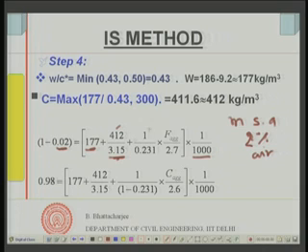So, that must be the volume occupied by all the ingredients, namely water, the cement, and the fine or total aggregate. This represents the total aggregate as we have seen earlier. Now, the volume of water is 177, because we know the density of water is 1000 kg per meter cube. So, if I had 177 kg of water, that would occupy, in meter cube, 177 divided by 1000, 0.177.